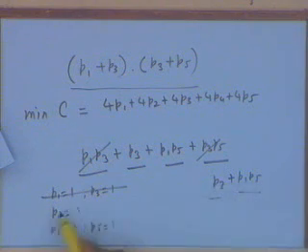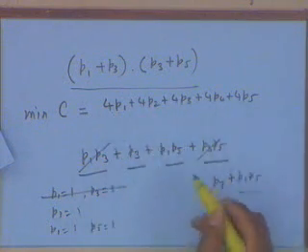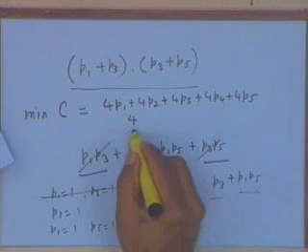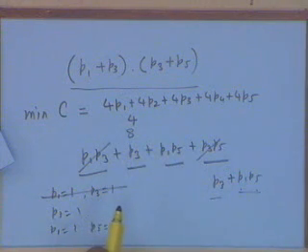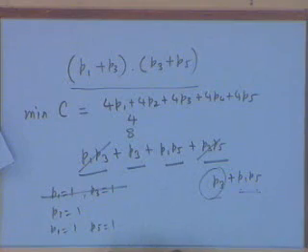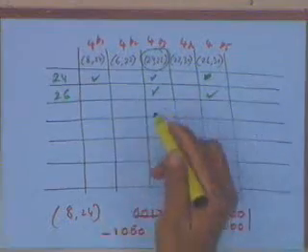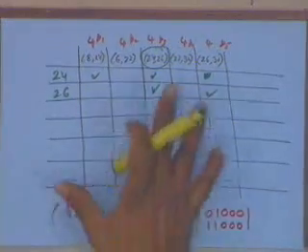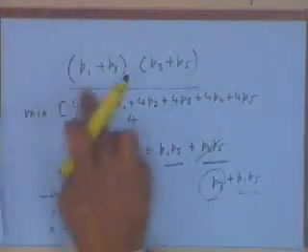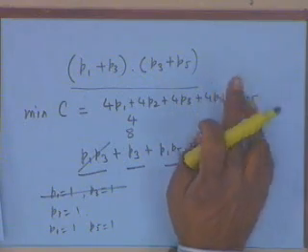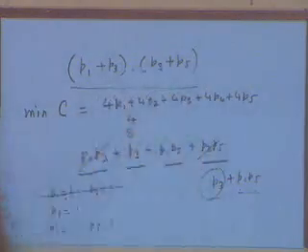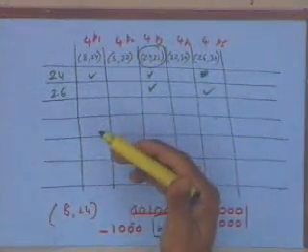These are the two options that I have to solve. If I take P3 to be 1 and I evaluate the cost, what is the cost? 4. If I take both P1 and P5 to be 1 and I evaluate the cost? 8. So obviously P3 equal to 1 is the minimal solution. I can see this over here in this particular problem, but if we have a complex cover table, this cover table can also be solved by formulating a Boolean equation. This Boolean equation has nothing to do with the original Boolean equation we were trying to simplify. This comes after eliminating the essential prime implicants.